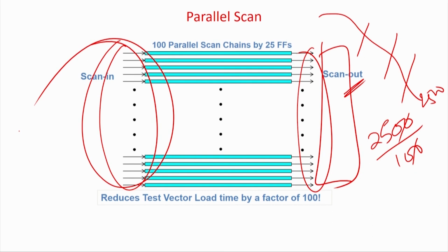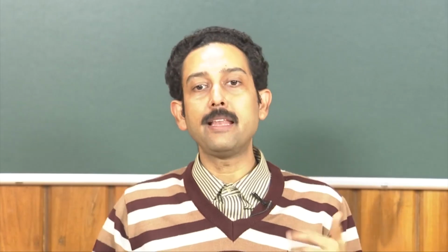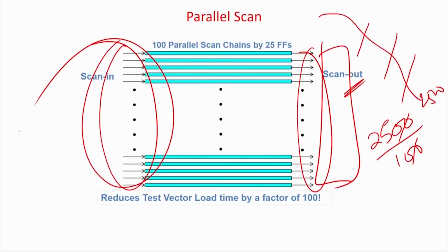We have already seen we try to reduce the test patterns by this width, so that basically the number of pins of your automatic test equipment reduces. So again, as I told you, there is a lot of trade-off. For very large circuits or circuits which have a very long scan chain, people try to parallelize. But how much depends on the amount of time you will save and the extra amount of pin outs you can spare. If you have a lot of pin outs to spare, you make a very large number of parallel scans, so you can load faster, but of course your pin outs will be higher. So that is another way of optimization, to find out basically what is the number of extra pins you have and how much speed you require to load it.